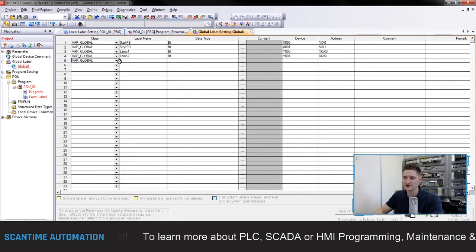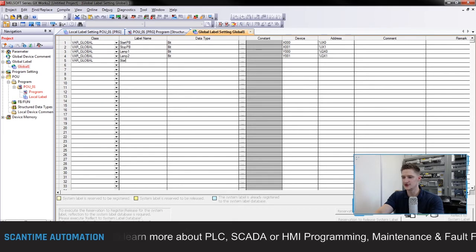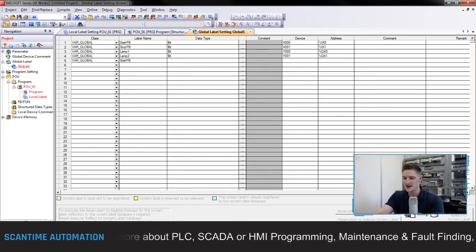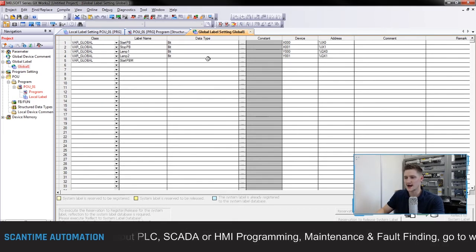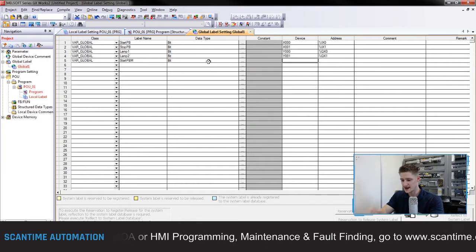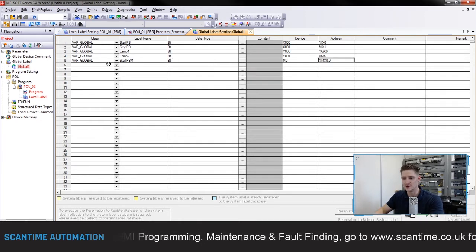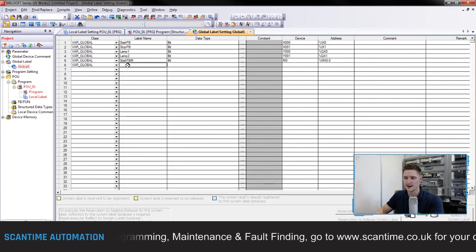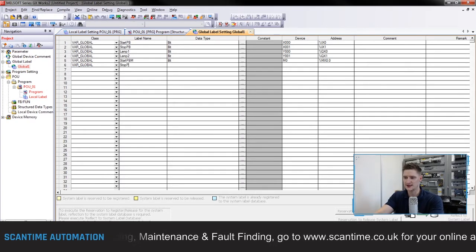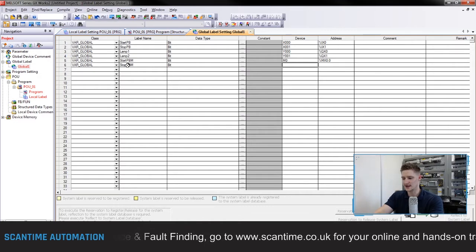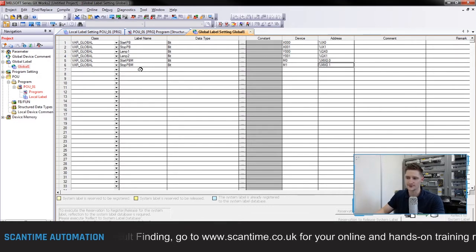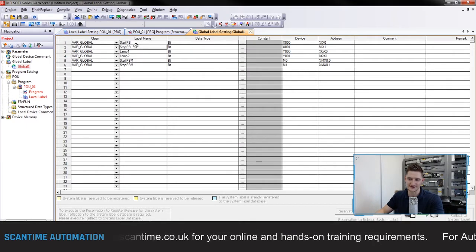So again, just go to Var Global, and then we'll call this Start PB M, and we'll leave this as a bit, and this will be assigned to M0. Then again we'll create another one, and this will be Stop PB M, and this will be a bit, and we'll tie this to M1. So we'll actually use these two inside of the program instead of using the physical input addressing, as we don't have any push buttons to press here.